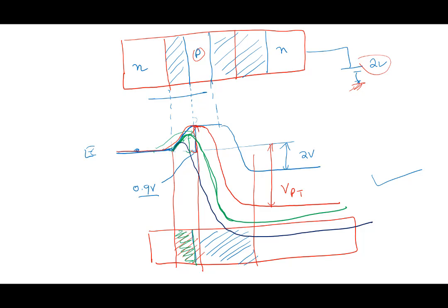And the electrons have an easy time going here. So what happens is the transistor is supposed to be off, but the moment punch through occurs, a lot of current can begin to flow. A little bit more voltage, the barrier gets reduced, and the current begins to increase.